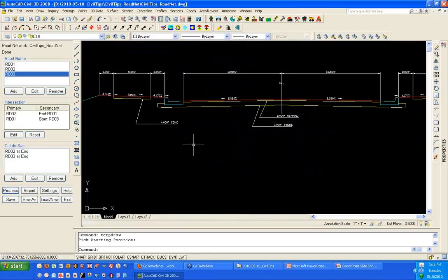And you can see how nice this is. Again, coming from a design from production, knowing how these typical templates, typical cross-sections are normally put together in a pinch when we're in a hurry trying to get a set of plans out the door. Normally, you'll say, you know, where can I find a typical template? Well, you go back to that one we worked on 6 months ago and just bring it in, copy it over from that drawing, and the only thing different is we're using 1.5 inches of asphalt instead of 2 inches. Just make the text change and go with it.